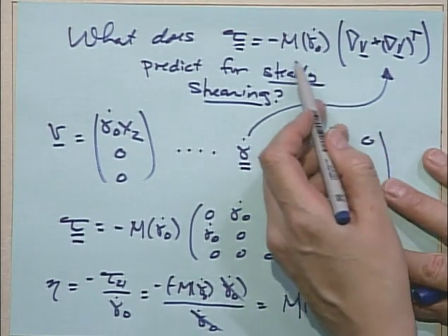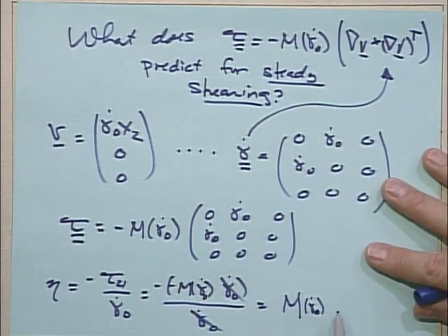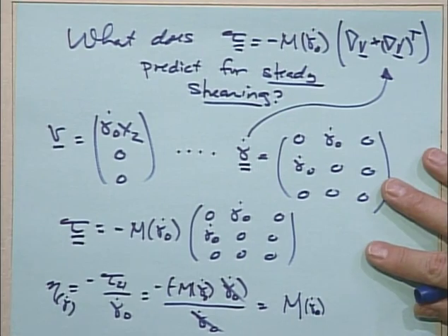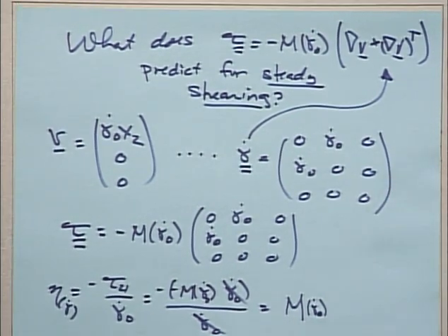So whatever function we put out front, that's the function that we predict. So we can get smart and just put out front what we know the material does. Okay? We can just invent a function, m, and make it slope downward at high shear rates and come to a constant value at low shear rates. Just put the answer right in. Very appealing. We know it's going to come out right.